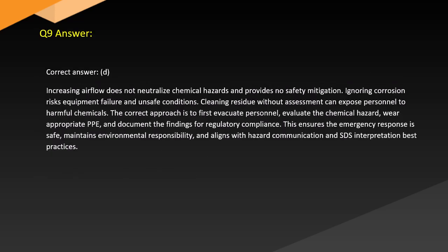Answer. Correct answer: A. Increasing airflow does not neutralize chemical hazards and provides no safety mitigation. Ignoring corrosion risks equipment failure and unsafe conditions. Cleaning residue without assessment can expose personnel to harmful chemicals. The correct approach is to first evacuate personnel, evaluate the chemical hazard, wear appropriate PPE, and document the findings for regulatory compliance. This ensures the emergency response is safe, maintains environmental responsibility, and aligns with hazard communication and SDS interpretation best practices.